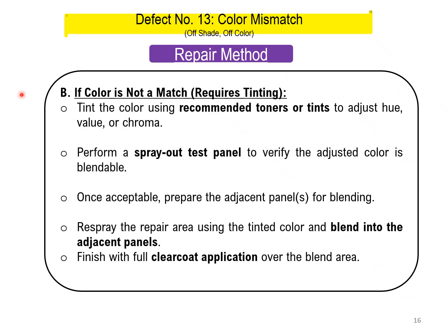If the color is not matched, then it requires tinting. Tint the color using recommended toners or tint to adjust hue, value, or chroma. Perform a spray out test panel to verify the adjusted color is blendable.